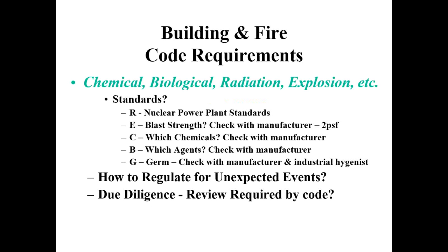Other testing and standards: most of the Firestops were developed from the nuclear power plant industry from the 1970s. So you'll find that many of the products may have radiation resistance. Ask the manufacturer. The International Building Code for high-rise buildings has a blast resistance. Check with the manufacturer to see what the Firestop blast resistance is. Some of them are very chemical resistant, some are not. Check with the manufacturer to see if the physical properties of the products match up with the conditions of the building. And then biological agents, germs.